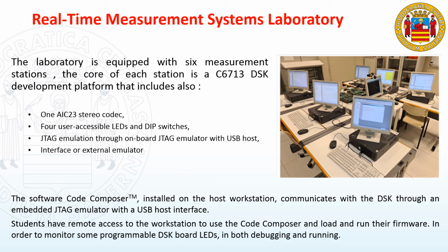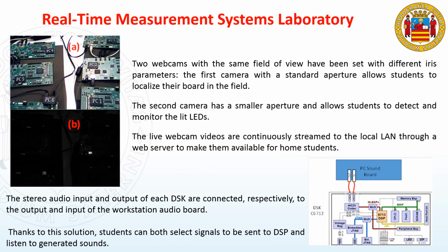The last remote laboratory didactic experience presented here is the Real-Time Measurement System Laboratory. In this laboratory, 6 measurement stations were equipped with a suitable DSP development platform, each of them provided with AIC23 stereo codecs, user-accessible LEDs and DIP switches. The 6 workstations were provided with the software Code Composer, which communicates with the development boards using the USB JTAG interface, allowing the load and debug of programmed firmware. In addition, in these laboratories, 2 webcams were employed.